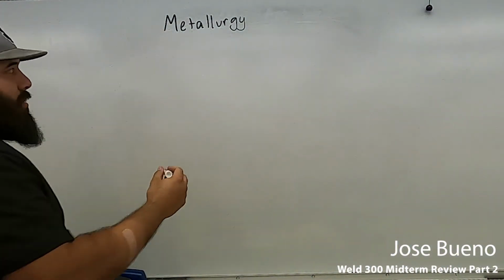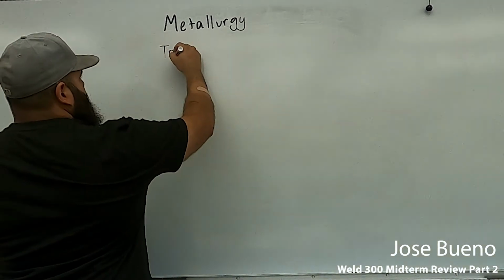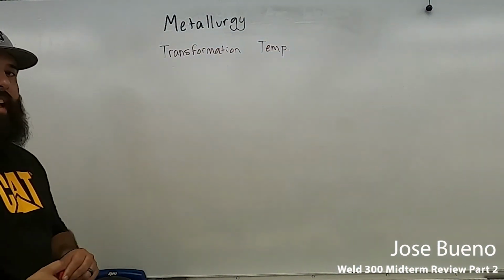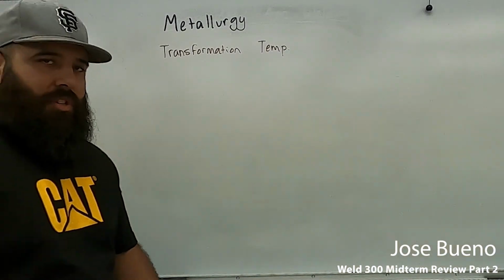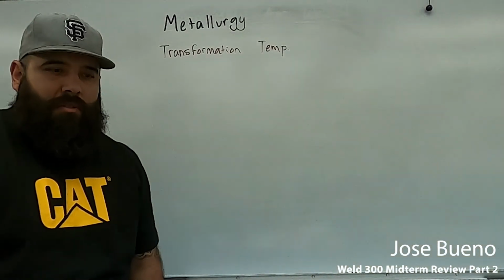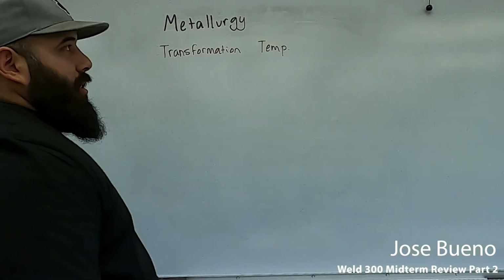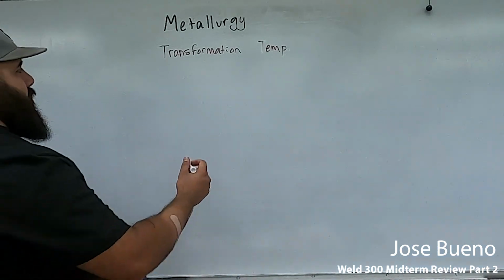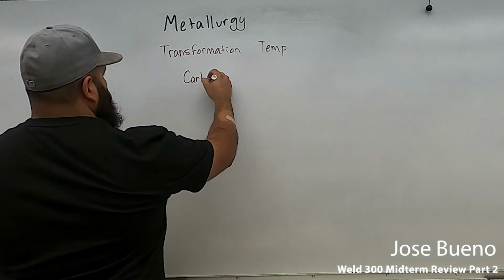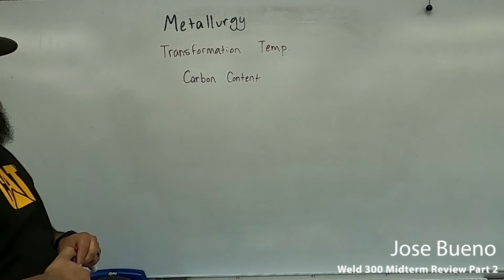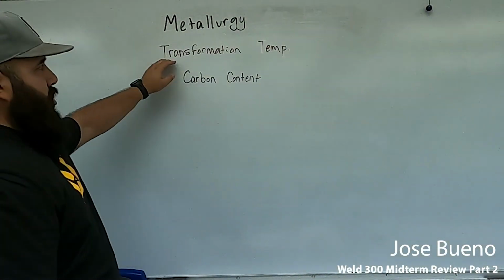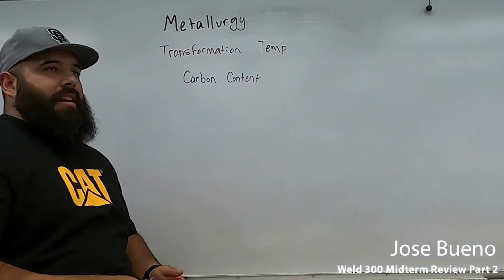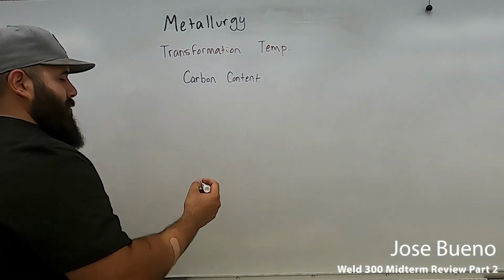So when we talk about transformation temperature, I'm sure you're all wondering what exactly is the transformation temperature for the steel that we're using. Now this gets a little tricky because transformation temperature is actually based on carbon content. So the carbon content is going to dictate the transformation temperature. There is a lower transformation temperature and there is an upper transformation temperature.